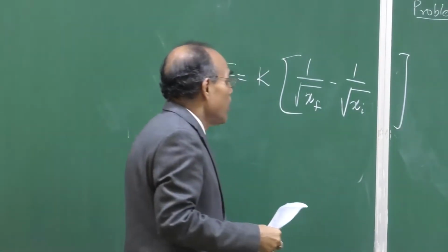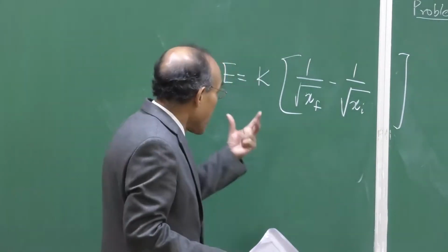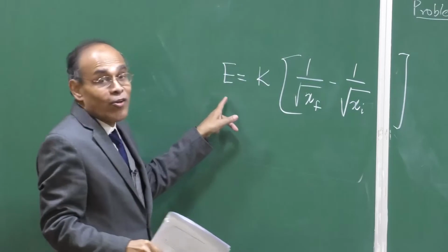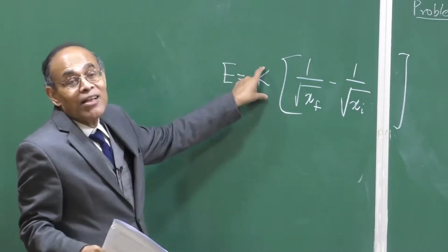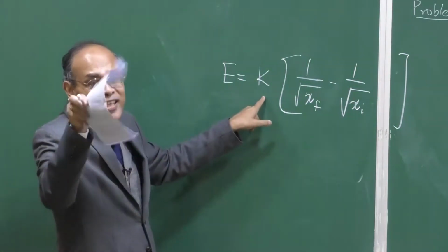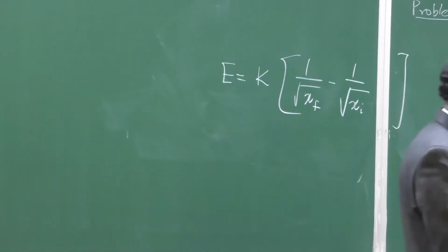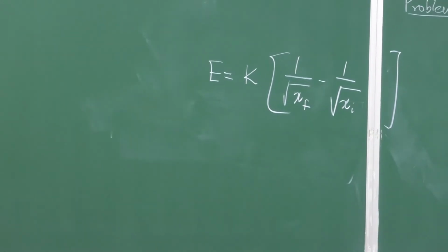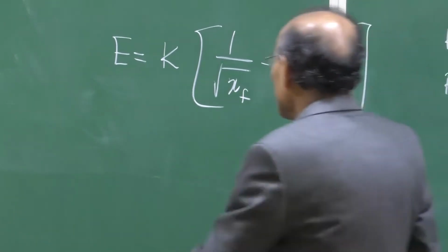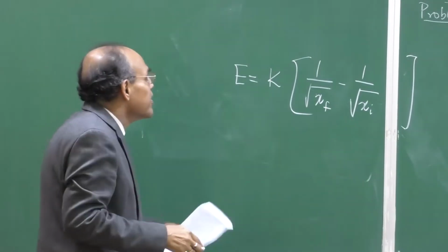So, for example, if you take galena, some ores are soft, some particles are hard. Therefore, even though you may have similar size reduction, the power consumption is not going to be the same, because there is a constant term here, and this constant depends on the crushing machine and on the nature of the ore or the material to be crushed. That tells us that even for similar size reductions, particles having different characteristics undergoing crushing in different machines will yield different energy requirements. Based on this, these constants have been defined.